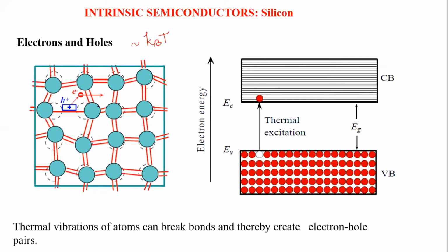So when this is taken in, T is the temperature, kB with suffix B is the Boltzmann constant. The atoms have to do some work. They will start to vibrate. During the vibration, if the vibration is so enormous, these bonds are elastic, so if it is more than that, the bond breaks, and the electron frees itself from the bonding. Like I described before, the absence of an electron in between, we call a hole.